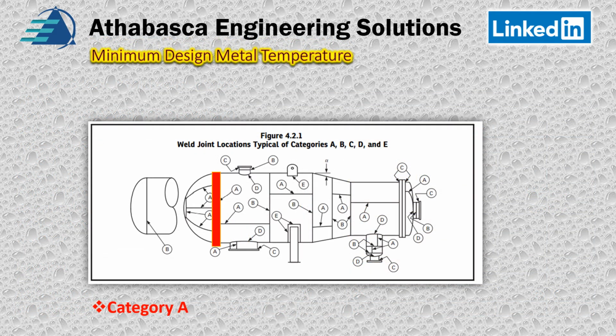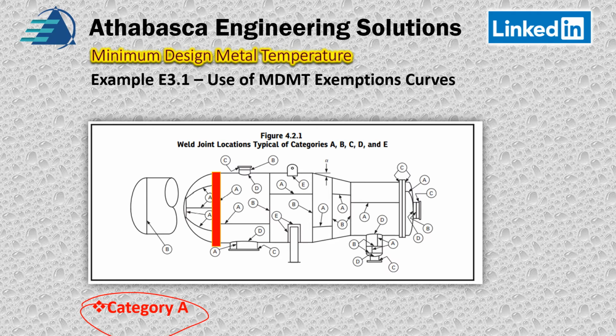Let's go back and derive why we call this Category A when we have a circumferential weld. A joint between a shell on one side and a head is classified by Figure 4.2.1 as a Category A connection. That's the same thing with Division 1.